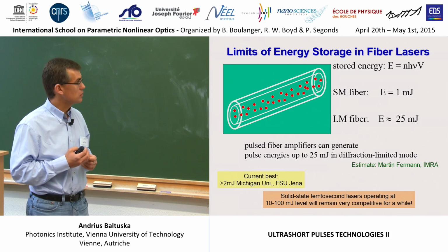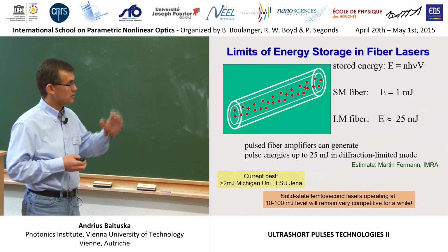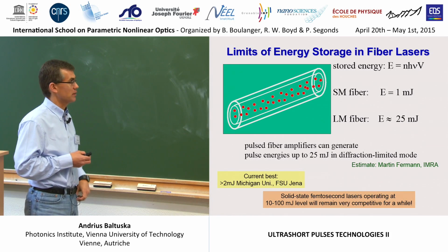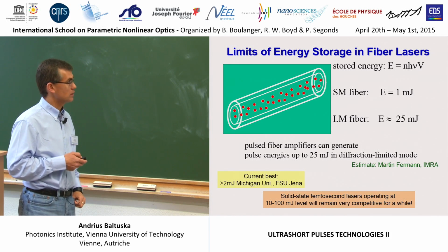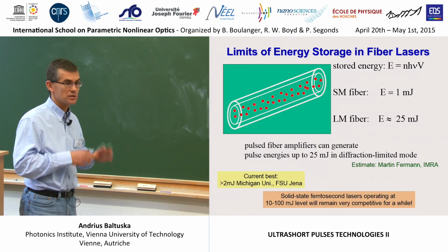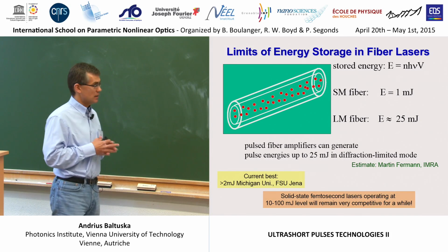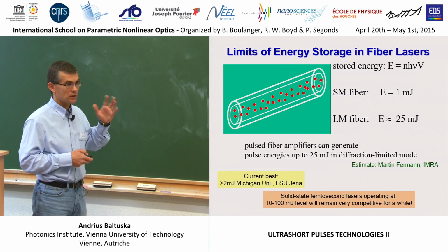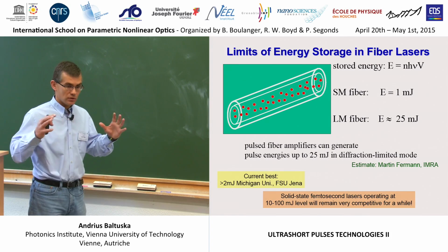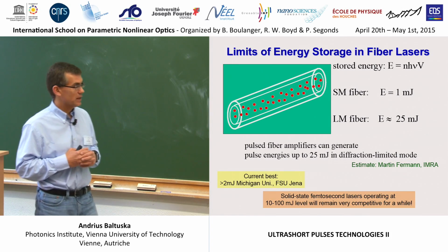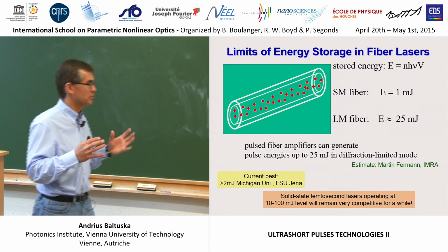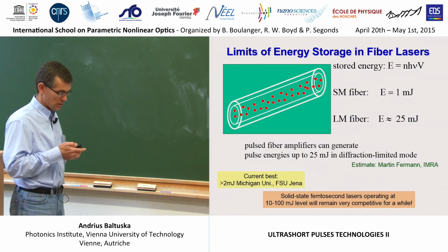But there is an issue that because of the limited cross-section of the fiber, you can only store that much energy. It doesn't matter whether you're producing nanosecond pulses or picosecond pulses. For single-mode fibers, it's on the order of single millijoules. If you go to large mode area fibers, you can increase that, but then you need to watch out what happens to the mode.